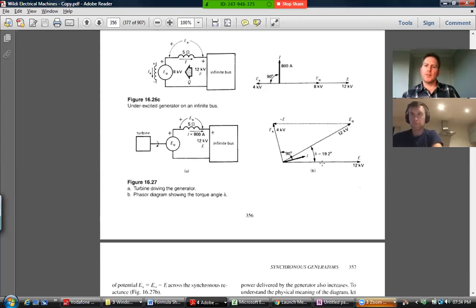But in this case, this is already a phase voltage. So simply, the circuit is per phase. So you just take this whole thing and it's happening 3 times over at the same time. So the power is just literally 3 times whatever you get from analyzing one phase.